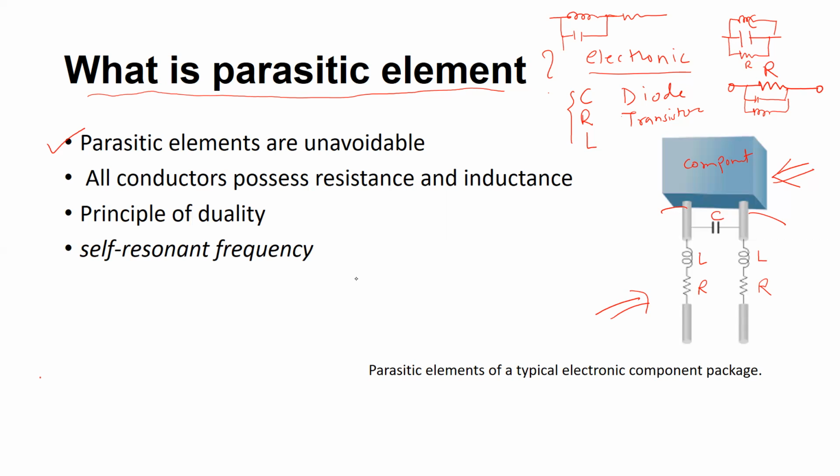So in electrical networks, a parasitic element is a circuit element, maybe a resistance, inductance, or capacitance, that is possessed by your component as shown, but it is not desirable for its intended purpose. We don't want these parasitics because we just want the component to function in its original way. Like I said, the resistor has unwanted capacitance, and there may be inductance as well.